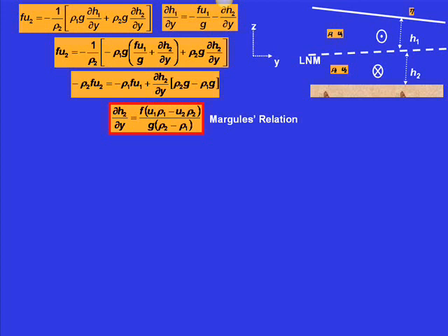Didn't it occur in mid-depth usually? Right, but what is the dynamic? I think he was the first to propose a dynamic balance along the estuary and across the estuary in that paper on the dynamic structure of a coastal plain estuary. It's what we talked about last time. What's the dynamic balance in a partially mixed estuary? Pressure gradient balanced by friction. If you remember, that's what Pritchard said with his observations. And he showed a table in which he calculated each of the different terms in the momentum balance, and he showed that those two are the leading order terms.